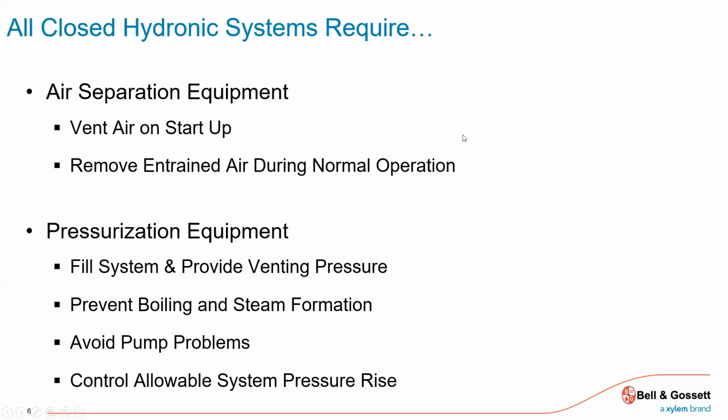So then all of a sudden, when they first introduced that, relief valves were dumping left and right because no one knew the correlation of the connection. So either they kind of poke a little hole in the check valve, which is really not what we're supposed to do, but more commonly put in a potable expansion tank that would then in turn accept that expansion, let the pressure rise, but not get to the relief valve that's now weeping water onto the floor. So in a closed loop, and in a potable system, when there's no draw, technically it's a closed loop as well. We want that expansion tank. Yeah. Yes.